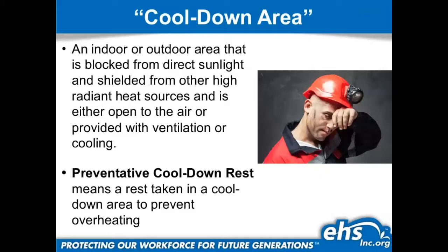With your cooldown area, primarily when we're talking outdoors, it needs to be provided. Now, does that mean just something like an easy-up? Not always. It needs to be a sufficient amount of shade. If we're talking indoors, we're probably talking about a break room or at least a covered overhang patio. Something that means for sure these guys are sitting down in a cool environment in the shade, without having to sit shoulder to shoulder, nearly sitting in each other's laps.